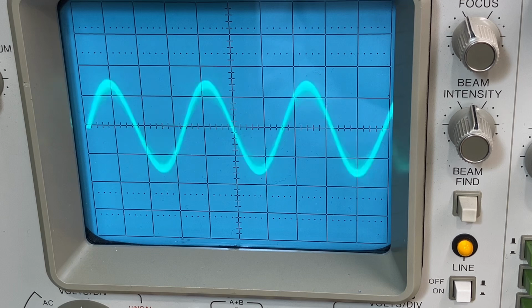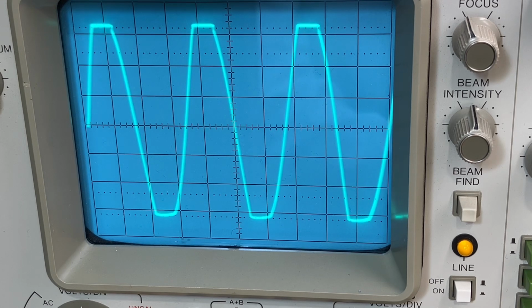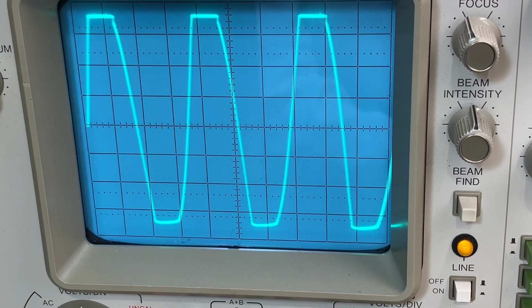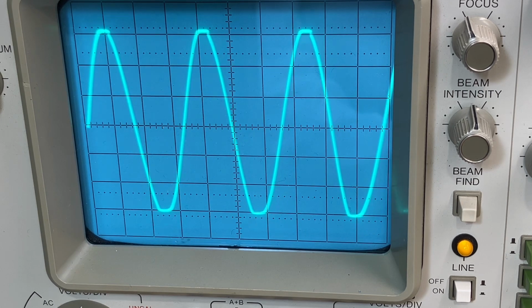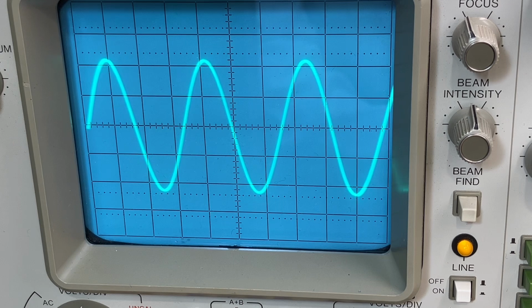And now I dial it down, and if I reduce the amount of negative feedback, we will start to get clipping as the oscillator swings to both supply rails, positive and negative. Somewhere in between those two extremes, we will have a nice clean sine wave with minimum distortion. Now, of course, I can't vary the frequency of this particular oscillator because I have fixed R's and C's, but it should be at about 1.5 kilohertz according to the calculation.